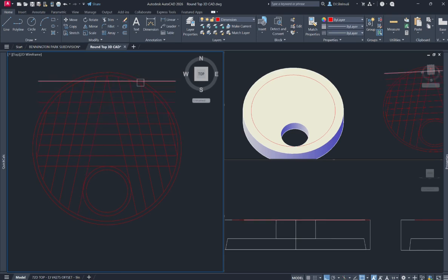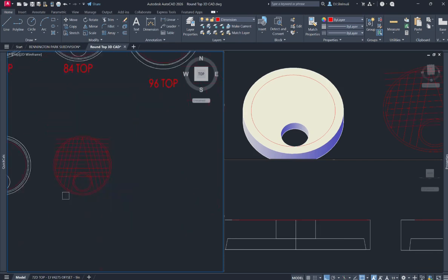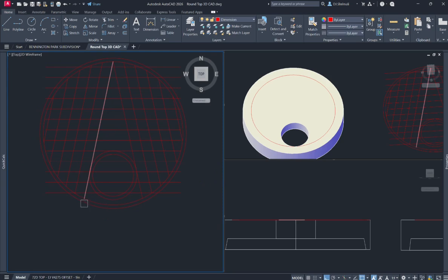So as you can see, we are drawing, and I'll show you the mirror command, the way how we can do it using the mirror command as well in short. So this is one method where you just draw each line using the trim extend command, and we'll see the other method using the mirror command in a while. So that's how we want to show our rebars.